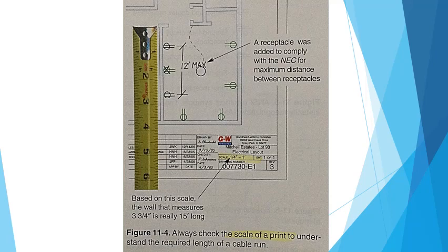A simple example is a 30 foot by 40 foot house that measures 7.5 inches by 10 inches on a drawing. The scale is 1/4 of an inch equals 1 foot. So every 1/4 inch measured on the drawing equals 1 foot. This means that the drawing is 1/48 the size of the actual house.